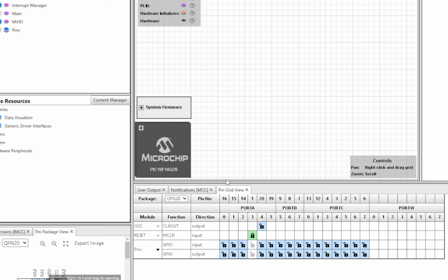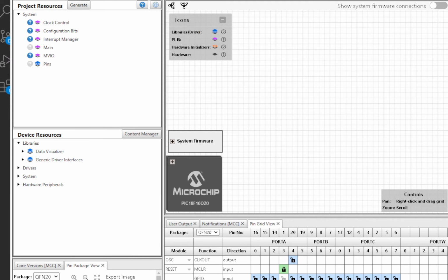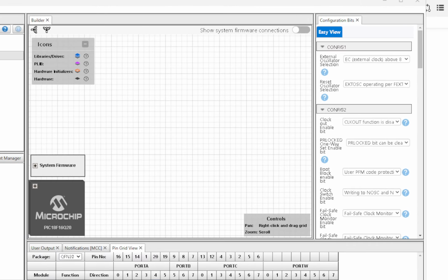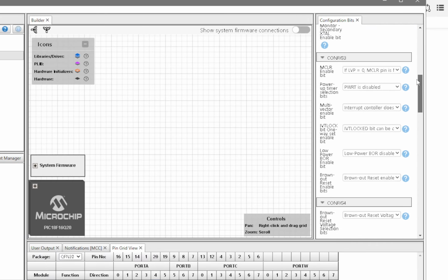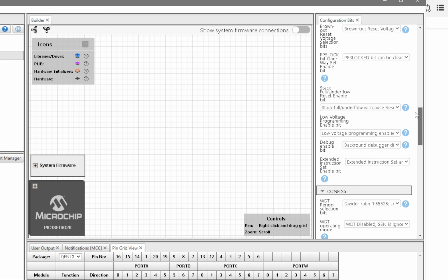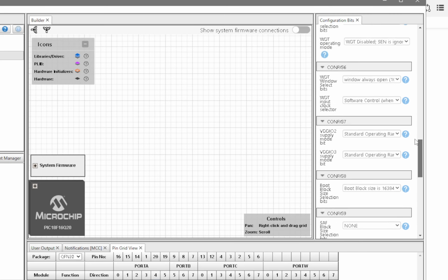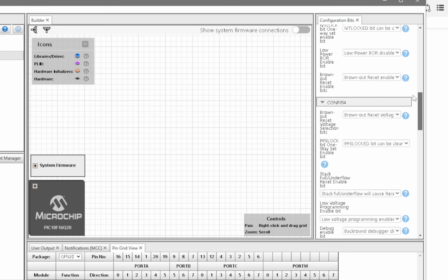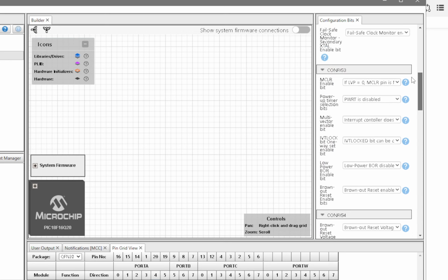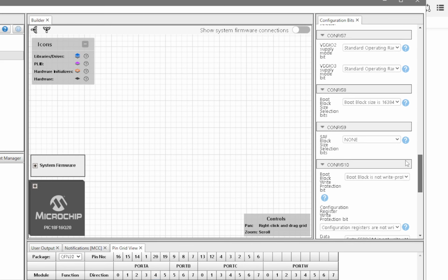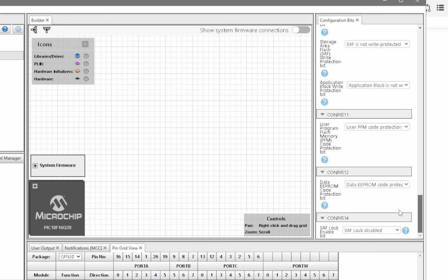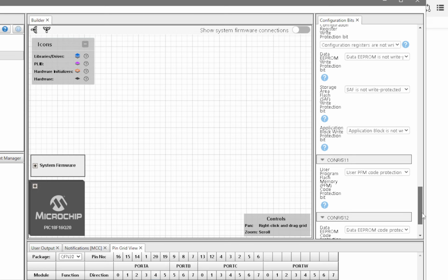If you want that as an input, you have to do two operations, and they're all inside the configuration bit. So if you go in here, click on the configuration bit, it will then load up on the left-hand side of the screen. I will cursor across onto the left-hand side of the screen so we can see it. A load of bits here we can set, and the first one we want to set is LVP programming, so we only use high voltage programming, not a problem. Now where is it? Which config number is it? Anyone like to guess?